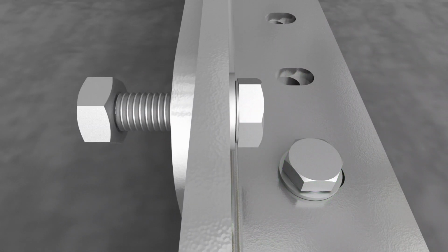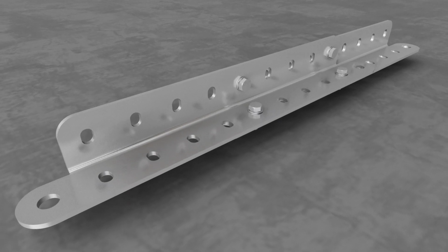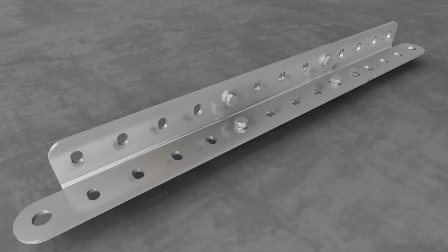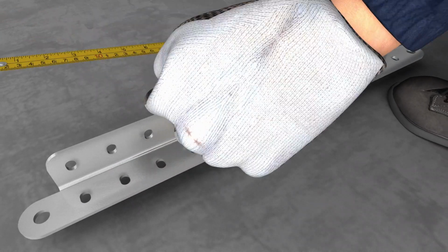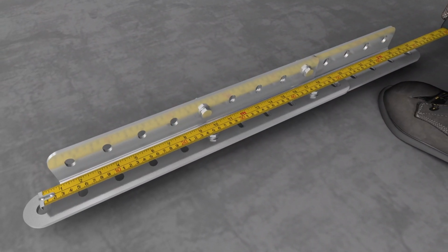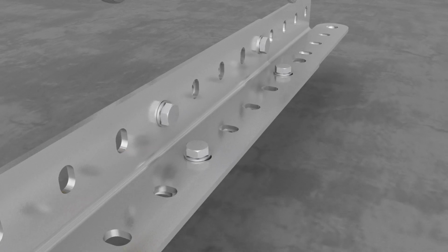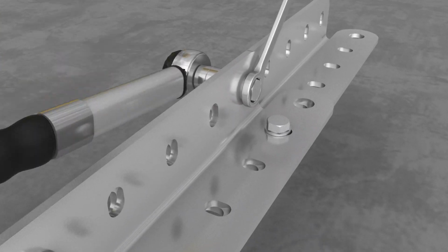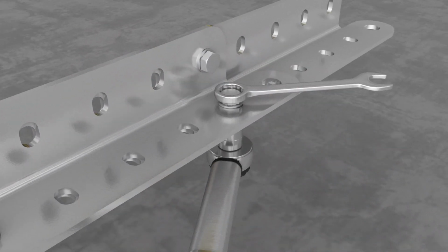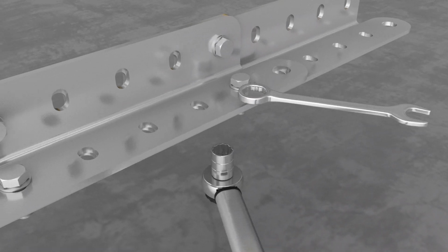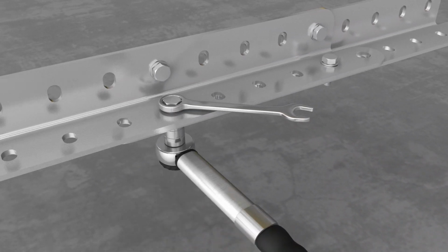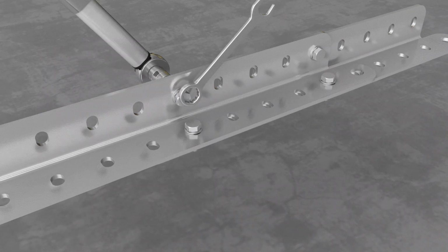Once the hanger link arm assemblies are loosely bolted together, prior to tightening, confirm their assembled length is correct as detailed in the system design specification. Tighten all bolt assemblies to the torque value shown in the torque settings table. Repeat the process for all remaining hanger link arm assemblies for each position.